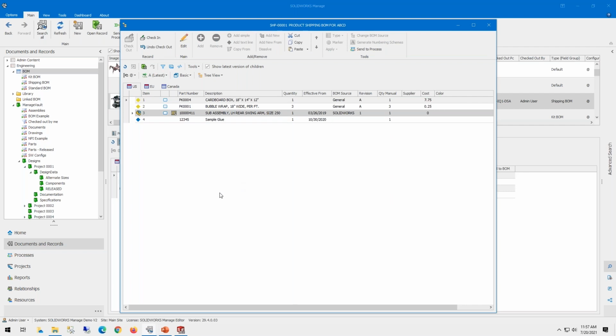And a question: does each variant BOM get a newly generated file name, or how is it distinguished during the exports? All the exports, again, are going out as XML files, and everything about that XML is going to be configurable, including how it's named. So you're going to define which variant you're pushing out in the export settings. All of that will be handled in a couple of places: one in the XML template that you generate itself, and then also in the export setup itself.